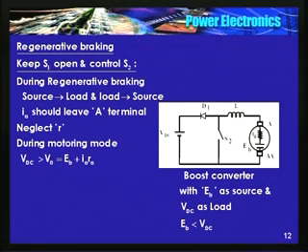Now just prior to closing S2, or just prior to regenerative braking, we are in the motoring mode, and we found that EB is less than VDC. Okay, in the motoring mode, when S1 was controlled, EB is less than VDC.